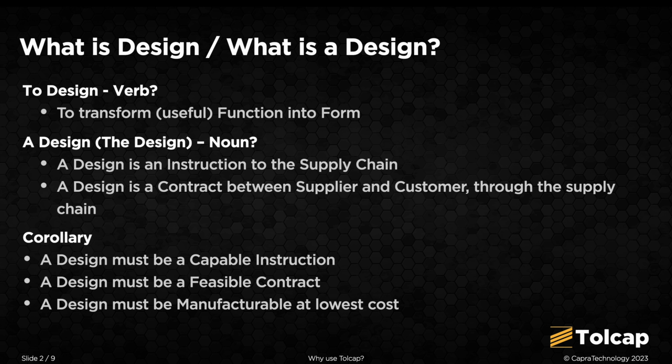Once you accept this definition of the design, the rather daunting consequence is that it is down to the designer to ensure that the contract is feasible and the instruction is capable. Much effort goes into analysing designs, even more into testing prototypes, to ensure the drawing captures every constraint necessary to ensure that the function is delivered. That's a large part of most designers' working day, and hard work though it is, the task is pretty much satisfactorily achieved. But often the process capability, or otherwise, of the design tolerances emerges only after the start of full production, when problems in assembly or of dimensions out of tolerance then have to be addressed. And of course, the design still has to be manufacturable at the lowest possible cost.